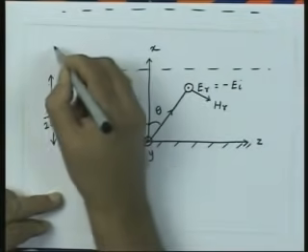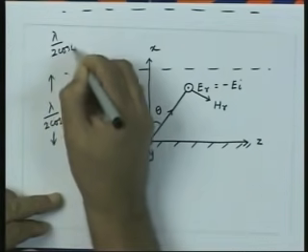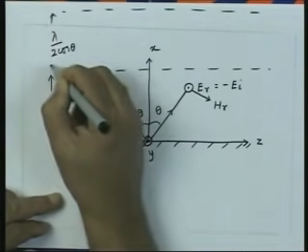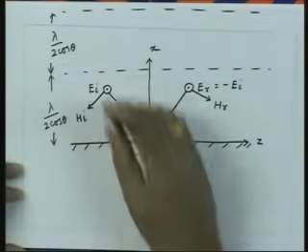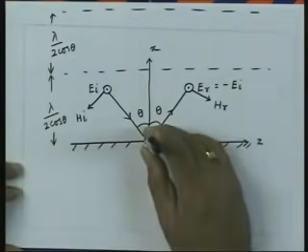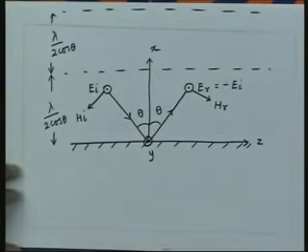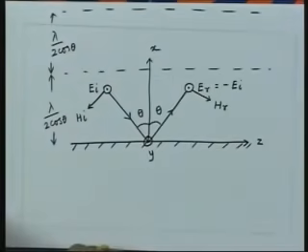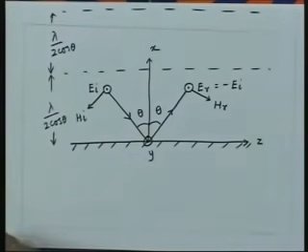So, this distance again is lambda upon 2 cos theta. So, this electric field which is tangential to this interface is 0 here, it is 0 here, it is 0 here, and so on. So, in fact, I have multiple locations of planes where this tangential component of the electric field will go to 0.